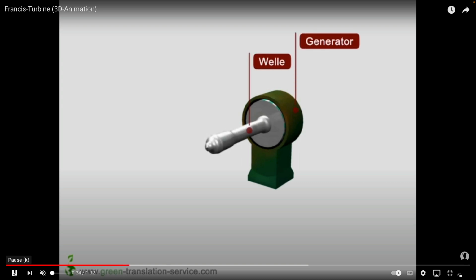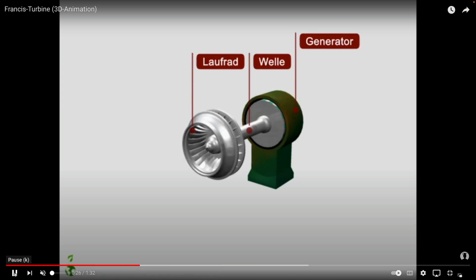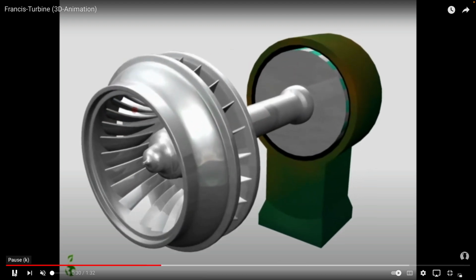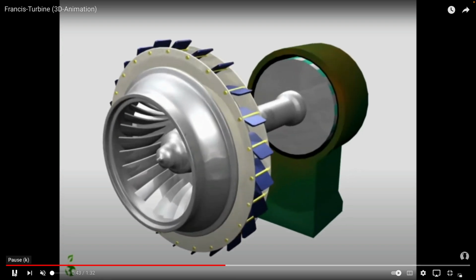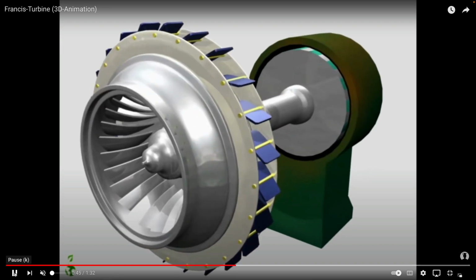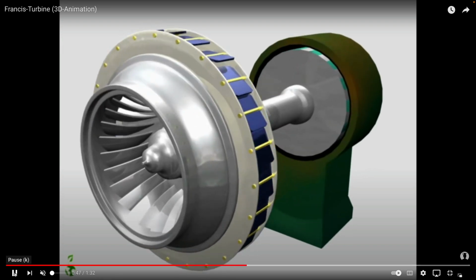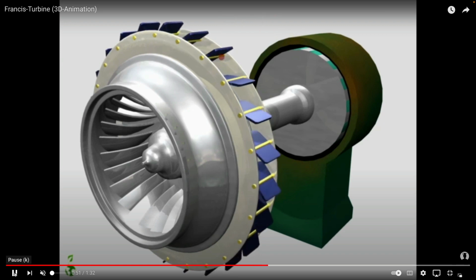Of course, in this transitional economy, one of the big things is storage. And so grid storage that's big enough to take lots of power to make up for power when the sun doesn't shine and when the wind doesn't blow, is to use things like pump storage. So you have an upper reservoir, lower reservoir. You pump up when you have excess power into the upper reservoir. You run it downwards when you need the power at nighttime, say, if you need it when the sun isn't shining.